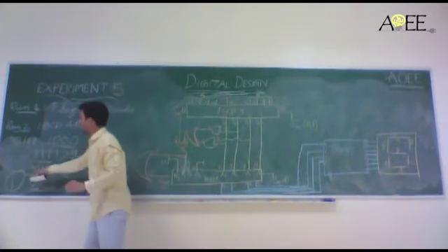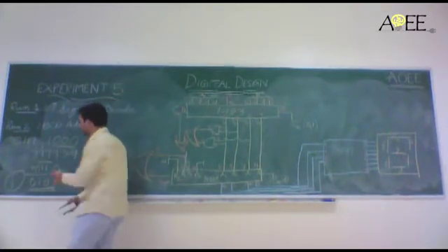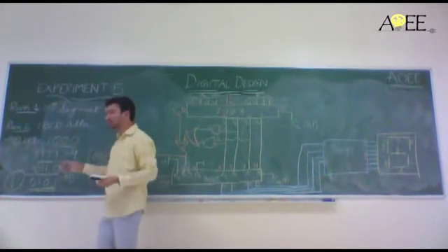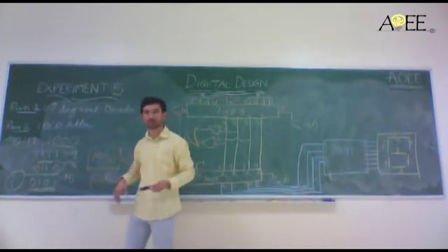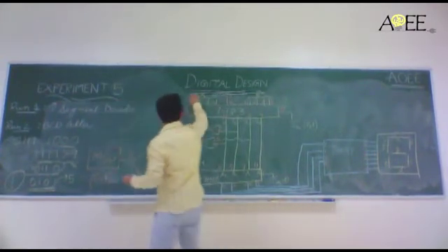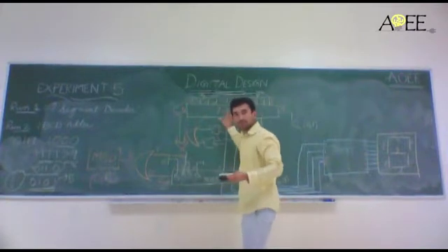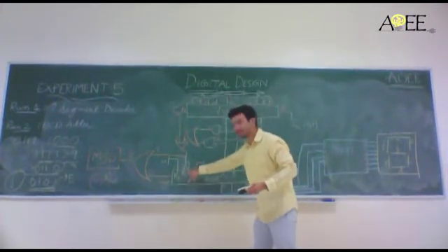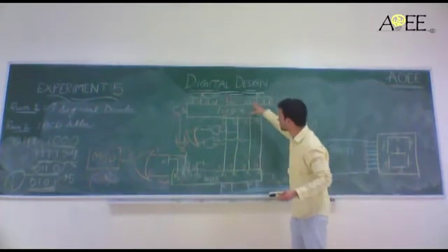And the idea behind adding 6 is genuine. We add 6 every time in order to convert any number which is not in BCD to BCD. So we have two numbers added, and we get a sum. We see the logic: if it is greater than 9, then add 6 to the sum.